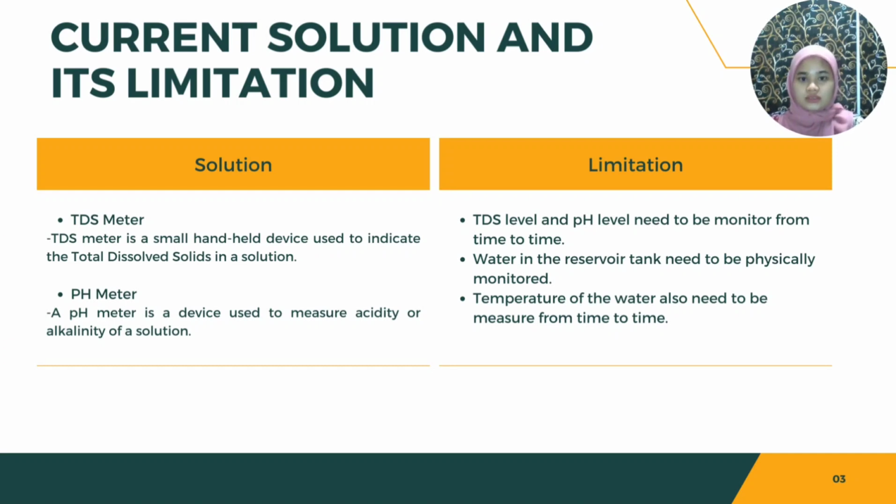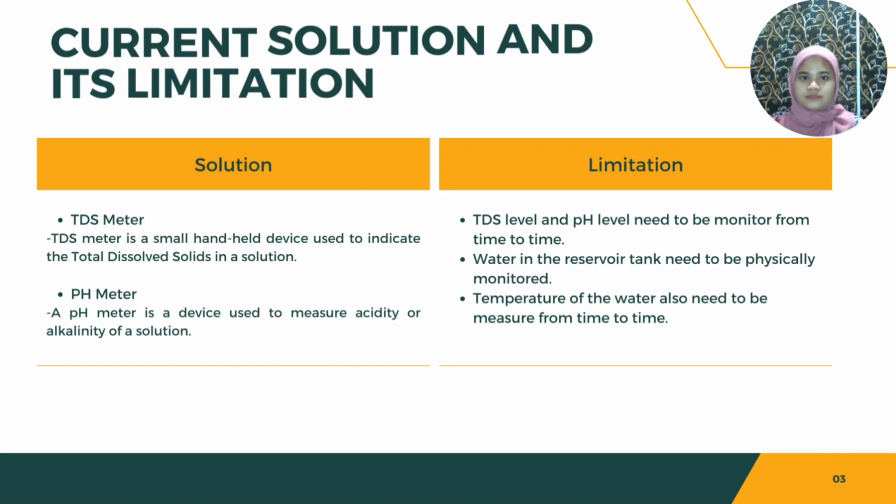For limitations, the TDS level and pH level need to be monitored from time to time. Water in the reservoir tank needs to be physically monitored. The temperature of the water also needs to be measured from time to time.